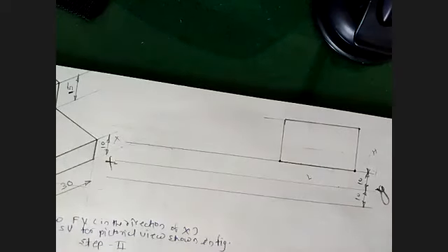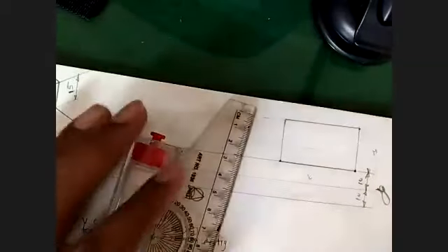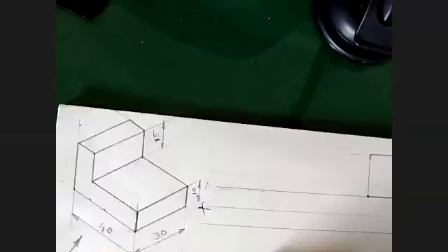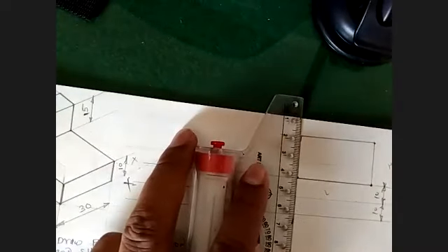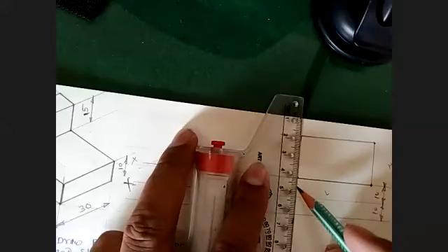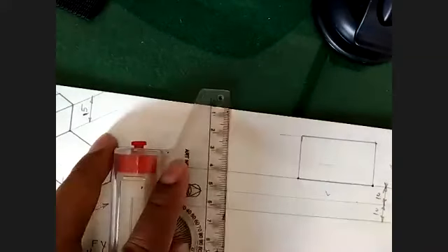Similarly, we have to construct the box for your top view, and you know that for the top view, the two dimensions are length and width. The length is already present in this front view boundary. So we'll take the projections by aligning this line with this one and take just a light line.